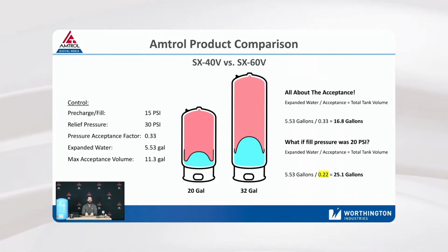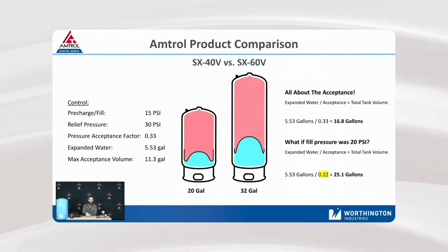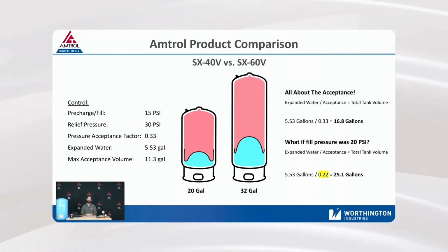It's very important. So as the pressure shrinks, we're going to need more volume, more air volume in the tank to make sure we're absorbing that, because of Boyle's law. They have to be proportional. In this case, it's inversely proportional. Less pressure range, more air volume. But if you run through the formulas, it'll always come out this way. It's just I'm trying to break it down to the point where I can kind of give a scenario for each reason why we change a variable, and then how that affects your tank sizing in the end. But in reality, if you went through tank sizing for every system, this would work its way out. You still see those final results, but this is why they're getting to that point on very, very similar system setups, but having to need two different tanks.